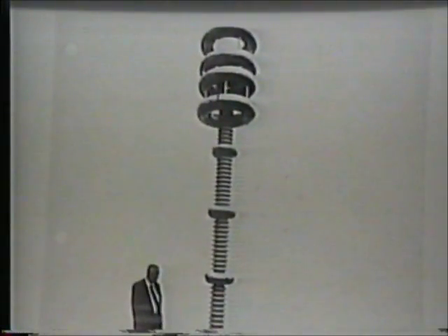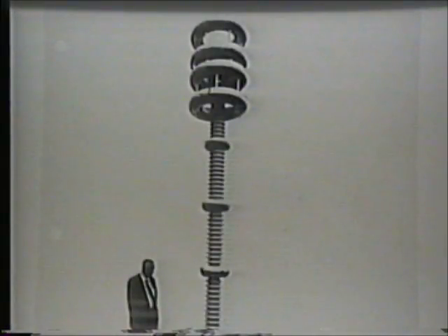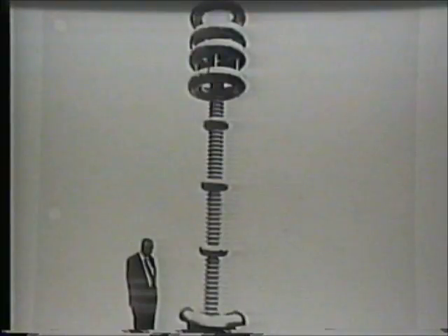Okay, in conventional measurement of electricity or high voltage, you have to use voltage dividers in order to get your instruments to work for you. Now, as the voltage gets higher, these voltage dividers get quite large. And in this case, in order to use conventional measuring instruments, this thing is more than 9 feet tall, and it's good for less than 1 million volts. So that means that you can measure up to 1 million volts with your regular measuring devices by using this divider in order to bring it down to where your instruments can work with it.